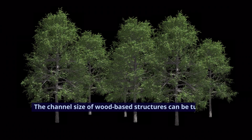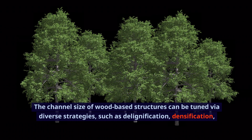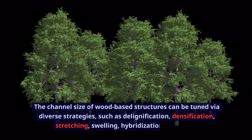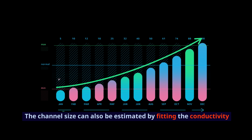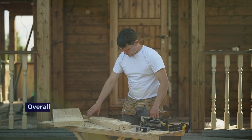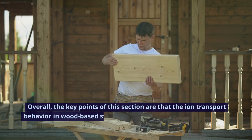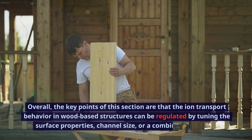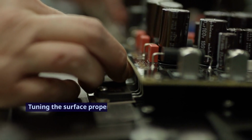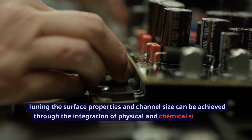The channel size of wood-based structures can be tuned via diverse strategies, such as delignification, densification, stretching, swelling, hybridization, and so on. The channel size can also be estimated by fitting the conductivity trend at various concentrations. Overall, the key points of this section are that the ion transport behavior in wood-based structures can be regulated by tuning the surface properties, channel size, or a combination of both. Tuning the surface properties and channel size can be achieved through the integration of physical and chemical structural modification.